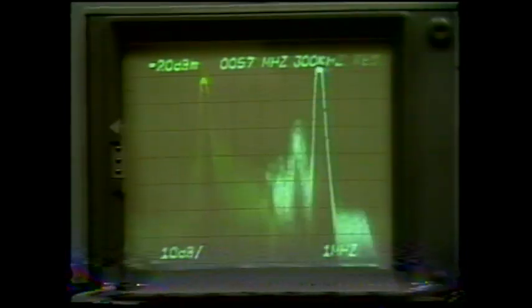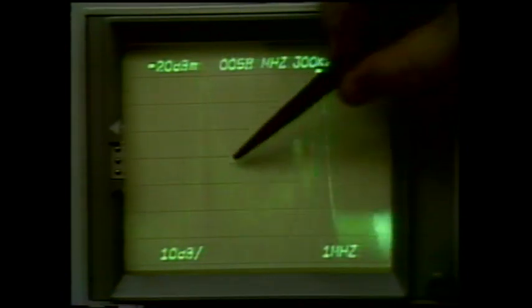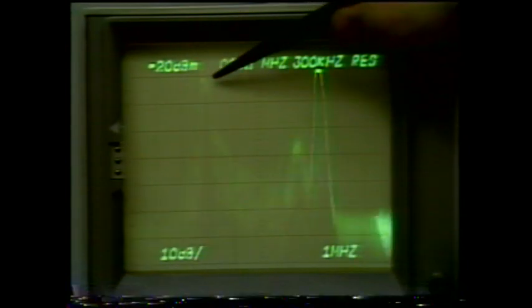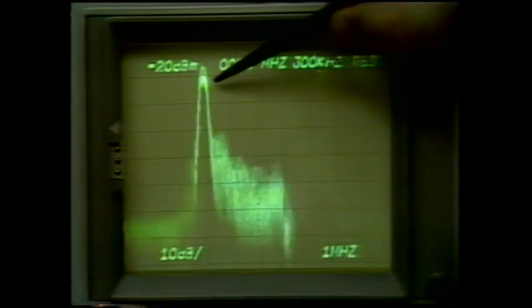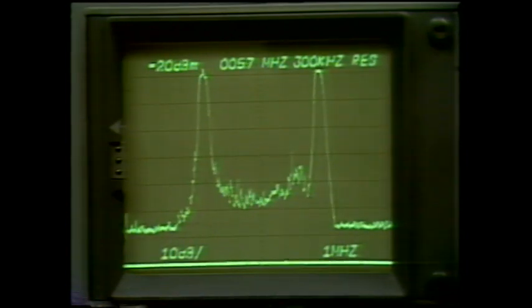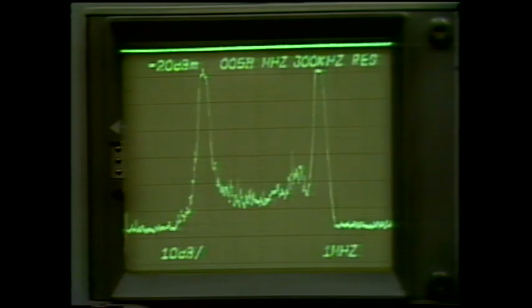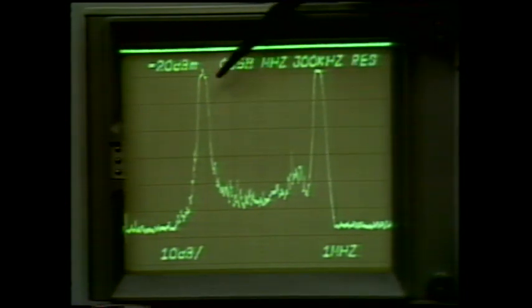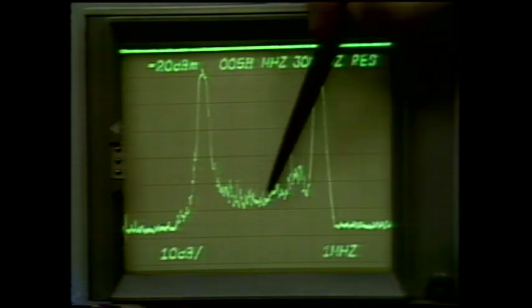First, we measure the amplitude of the peak video carrier, and this is the video carrier pulse, and we measure the peak amplitude at about -25 dBm. Now, to measure the noise, we'll switch to digital storage and digital averaging, moving the baseline clipper to the top of the screen, and we make the measurement midway between the vision carrier and the color subcarrier, somewhere here where the luminance level and the chrominance level is down in the noise.